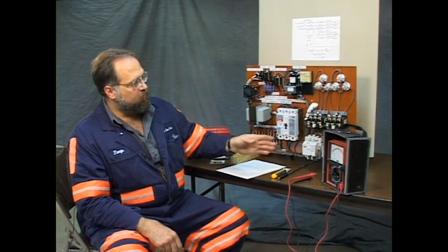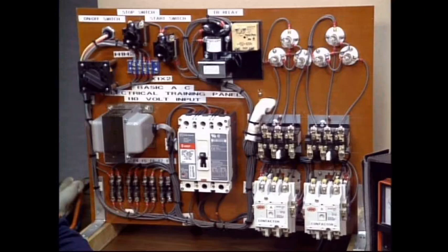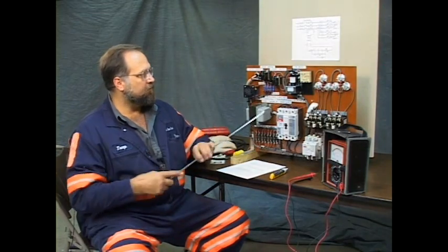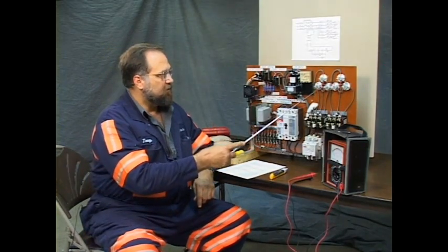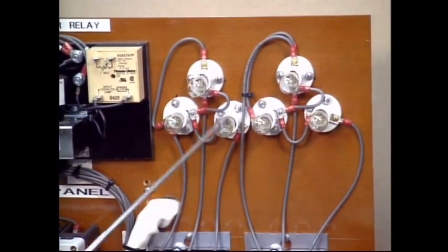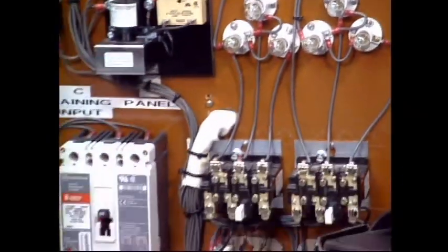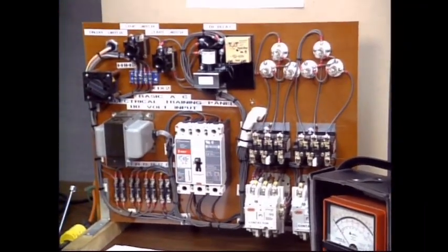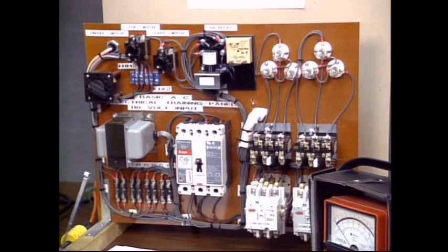We have two line starters. This type of panel is commonly found on a belt starter. It'll have two motors to run, an A motor and a B motor. The motors are illustrated on this panel by these lights. These 3 lights in this grouping on the left are for the A motor. The 3 lights in the grouping on the right are for the B motor. Each light symbolizes a phase, an energized phase. When the motor is started, it has 3 phases energized.